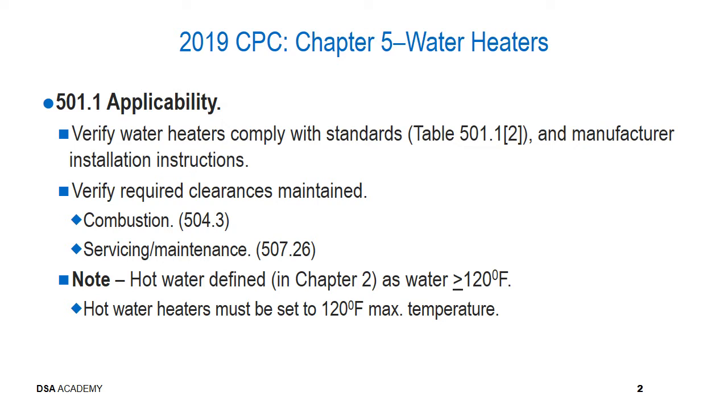So there is an explosive component to the pressures that are developed inside. They also have hot water in them, and they are generally fed with fuel gas. So that certainly warrants them having their own chapter within the CPC. You need to verify, obviously, that the materials received are correct, and the water heaters have got to comply with the standards. These are specifically addressed in Table 501.12.